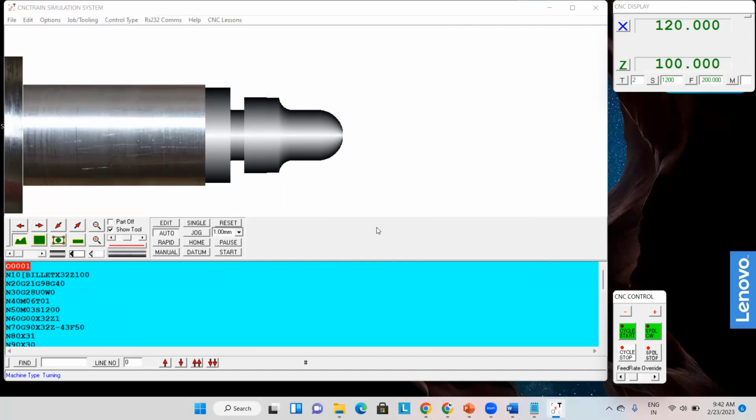So like this only, in industry CNC machine programmers check the CNC program. First of all, in the company, they give you one diagram. You read the diagram, you select the tools, the billet size, everything, and note it down in the operation sheet. Later, you start to write a CNC program manually with pen and paper.